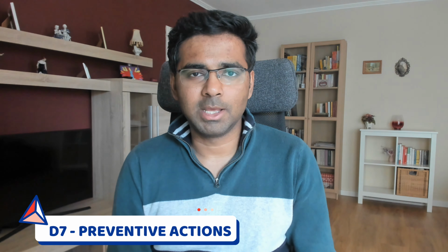The most common mistake many people and companies make is that they do the 8D process only until the D5. This stage is important to make sure that the issue does not reoccur in this product and also in the similar products where this issue can occur. In this stage, you update all the needed documents like technical drawings, FMEA, control plan, work instructions, and so on. And important is you don't update the documents only for this particular product, but for all the products in the product family or any product in your company where this problem could be possible.